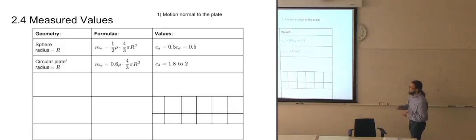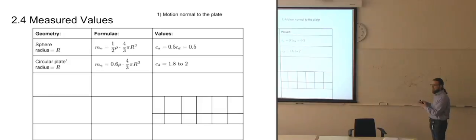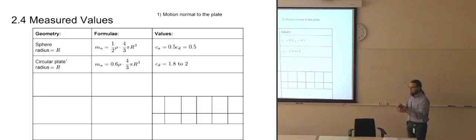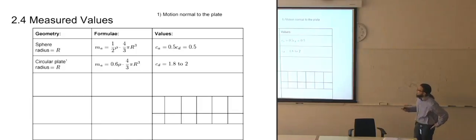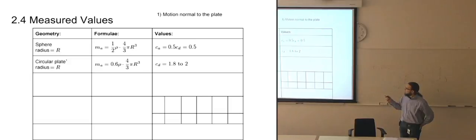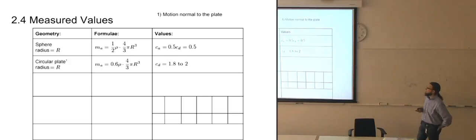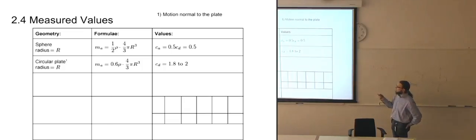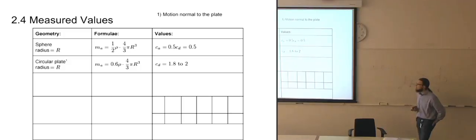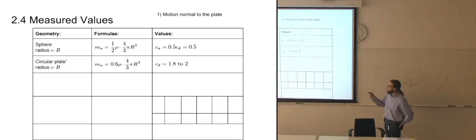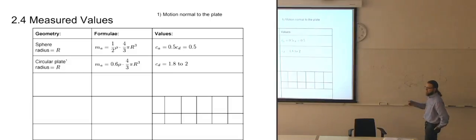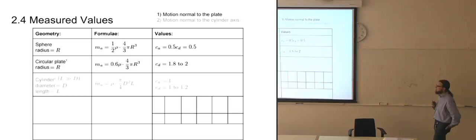And they've done at least hundreds of tests, if not thousands, on each of them to verify that the values are correct. So these are sort of the averages of the values that they've tested. And here it's a bit difficult to get, I'm guessing at least it was a bit difficult to calculate an added mass coefficient, so they've just put in a drag coefficient, 1.8 to 2. So then you suddenly have quite a lot of extra being put in for the force from the drag there.